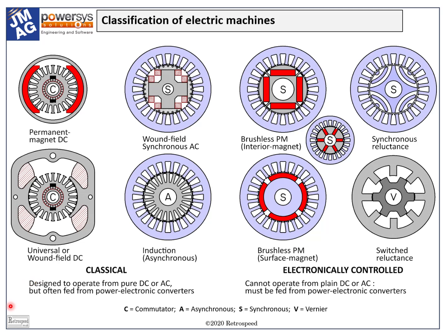Performance calculations, on the other hand, are concerned with the behavior of the machine once it has been built, and they almost always include modeling of the supply and the control as well as the load. At the simplest level, performance calculations use inductances, generated voltages, resistances, and other circuit variables such as currents and flux linkages, and mechanical variables such as torque and speed.